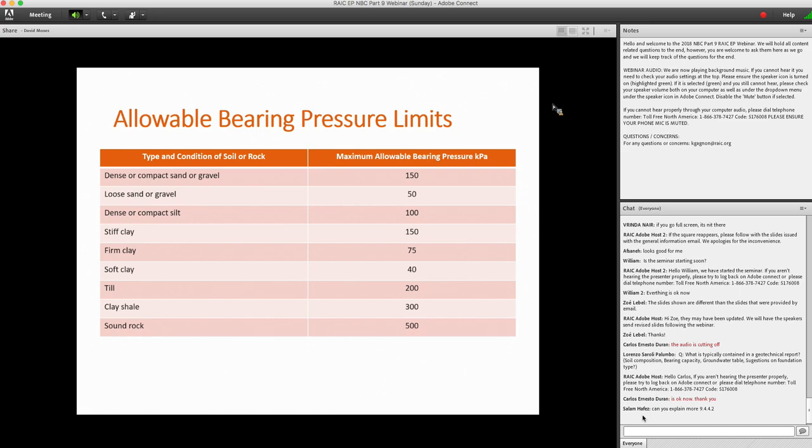And if they do boreholes, they'll be able to tell the makeup of different layers and stratification of the soils down below. They would also be able to tell you the groundwater table location, which can be important, and I'll get to that in just a minute. And they would probably also make a recommendation on the type of foundation to use. So if it would be a pile, a spread footing, or any other type of foundation that might be required.